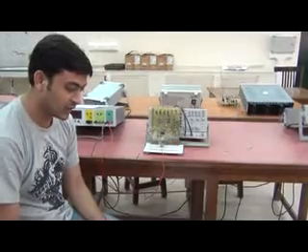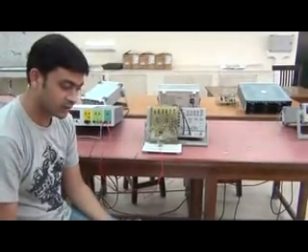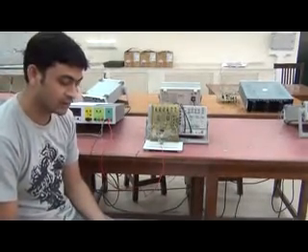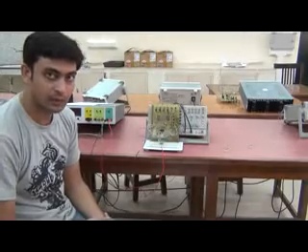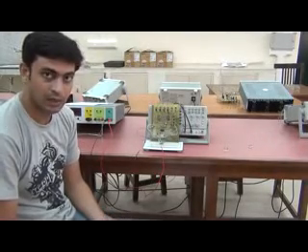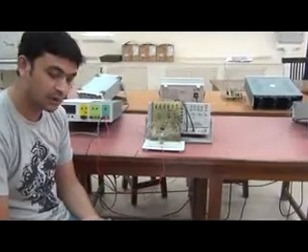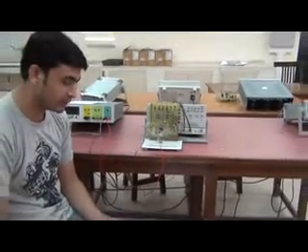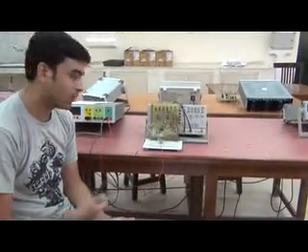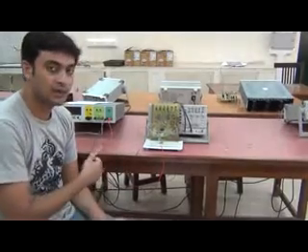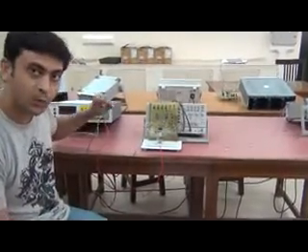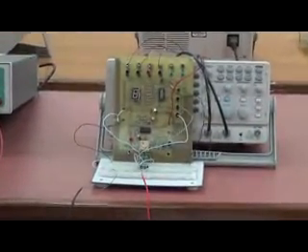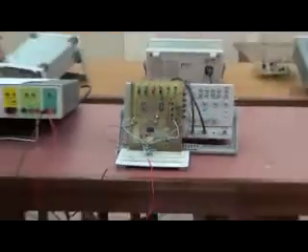For this case, we will have the MSB flip-flop's input as the complement of the LSB flip-flop's output, and the LSB input will be all 1, that is J and K will be 1 for the LSB flip-flop. So we have designed this synchronous counter on this breadboard, and we will verify it again on the digital test board, and the output will be verified using the digital 7-segment display. We will give the power supply from the power supply generator.